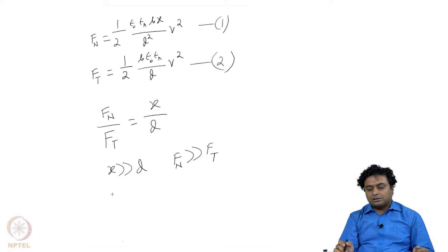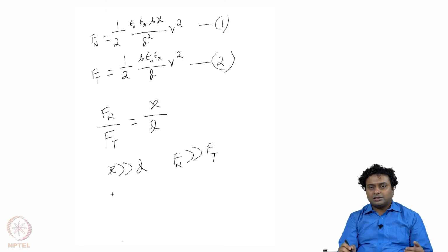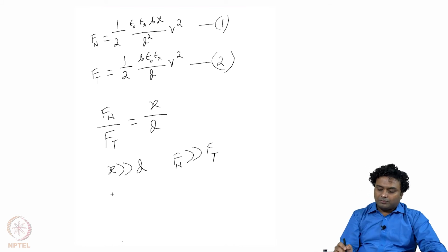But the gap between the two plates, or between two layers, has some microfabrication constraints, because of which we cannot make it very high. It will be a micrometer, or even a few nanometers, a few hundreds of nanometers, etc. So usually the d, which is the gap between two layers of our device, is very small.